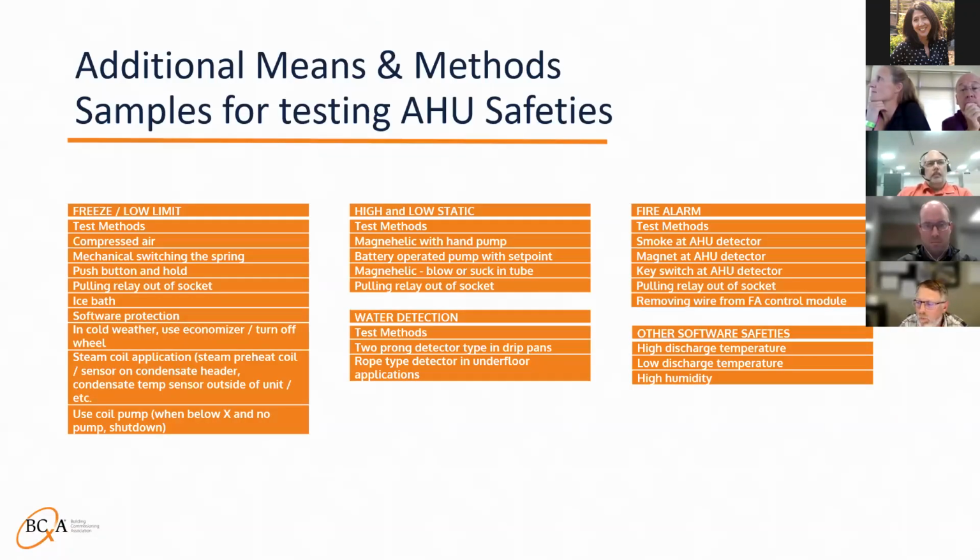There was another comment in here about ambient and set point to activate. I believe ASHRAE has your typical outdoor air conditions based on where your location is. Outdoor air is somewhere in the 300 to 450, 350 to 450 ppm. They want the activation to be 400 to 500 ppm above ambient. So that's where our activation set point comes from.